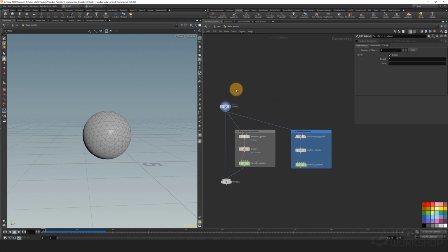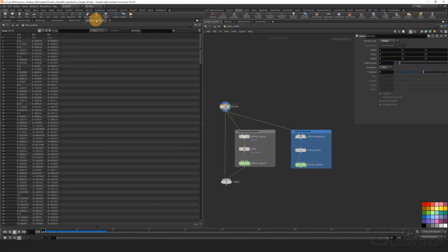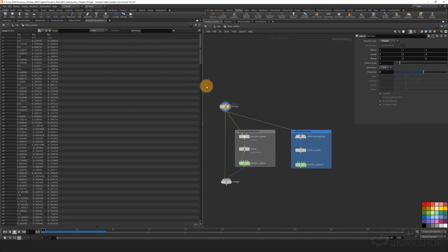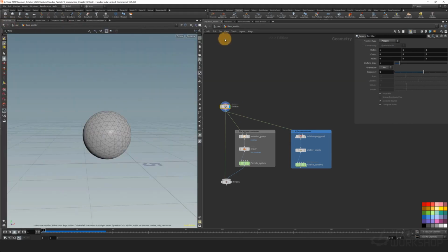We need the Cd attributes, because I like to control the density with a texture. But you see inside the geometry spreadsheet, actually we have all points inside the sphere, and we have just the P attribute. You can see the P attribute also there. We have 1 point attribute, the P, and it's a 3 information float. So we have P X, P Y, and P Z, just the coordinates for each point. We have no UV, we have nothing. So we need to create something. By the way, let's go back there.